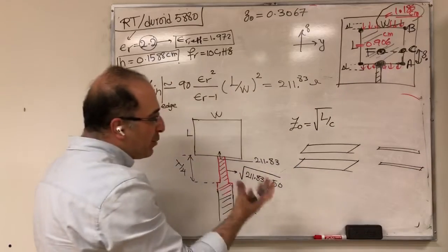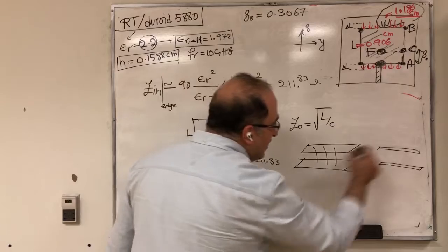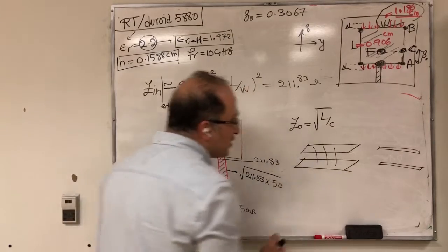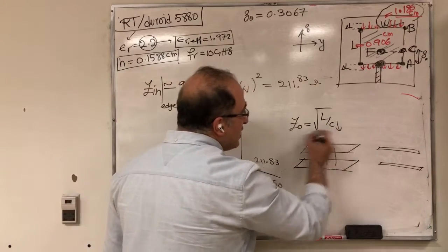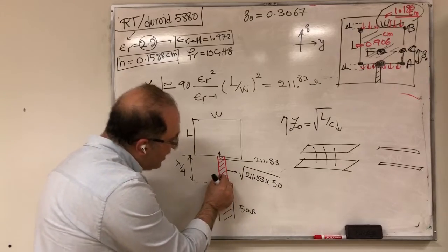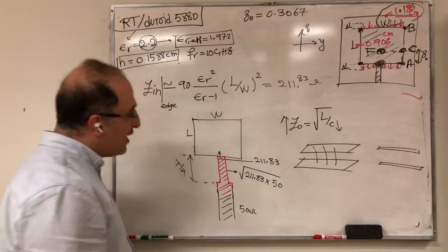In terms of capacitance value between these, if the line becomes thinner, the capacitance value drops because now storage becomes more difficult. So if capacitance drops, Z naught increases. So that's why you have it a little bit thinner, and therefore the characteristic impedance goes up.